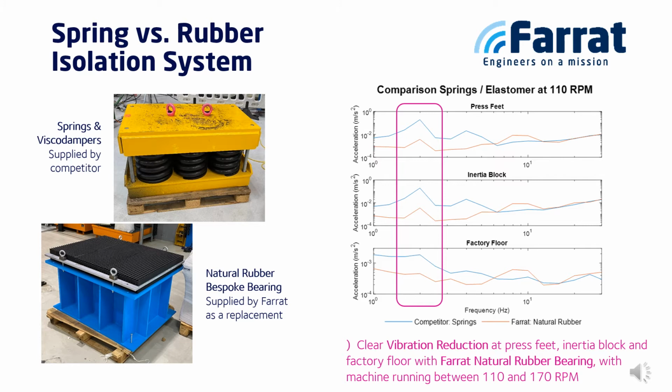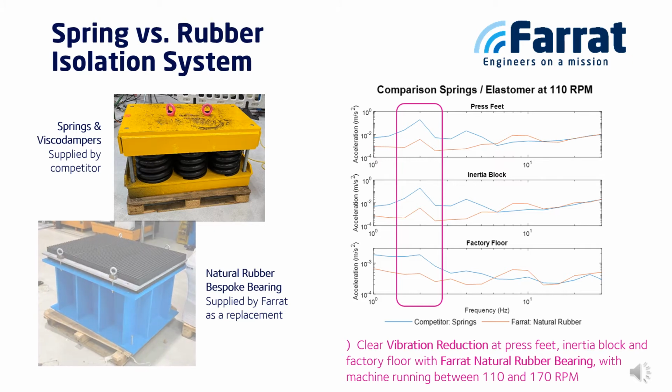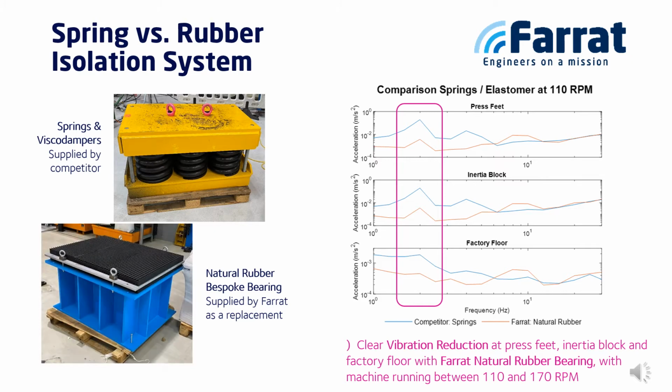Farrat was asked to provide a solution that would reduce the excessive movement of the press while maintaining a quiet environment for the neighbouring buildings. So the challenge was to stiffen the overall system while preventing excessive vibrations being transmitted around. In order to solve both parts of the equation, the engineering team worked on bespoke bearings made of a steel base and 2 layers of natural rubber, as presented in the picture.